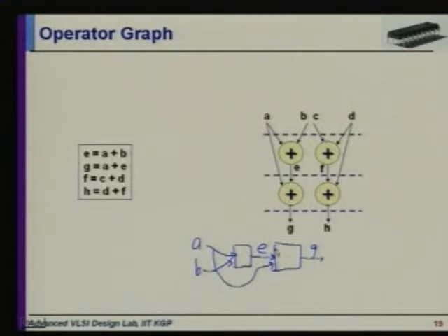Now you may say that this whole thing can execute in one clock cycle, but that's going to make your clock cycle width larger, right? Making your clock cycle width larger may actually slow down several other parts of the circuit which could have worked using a faster clock.